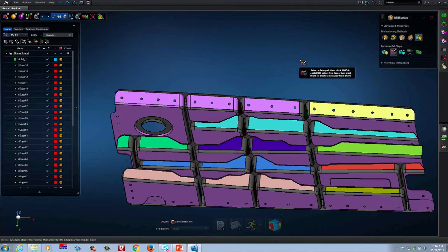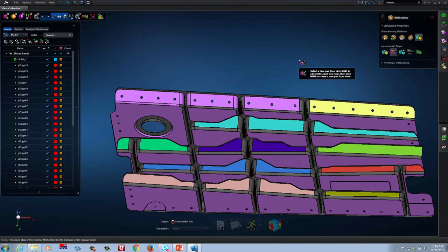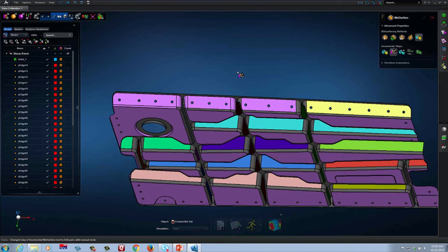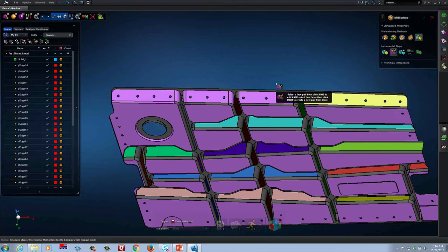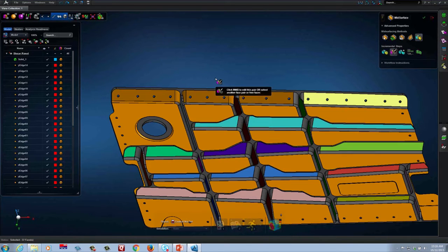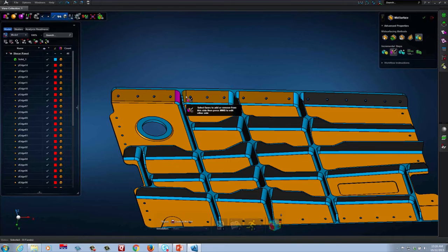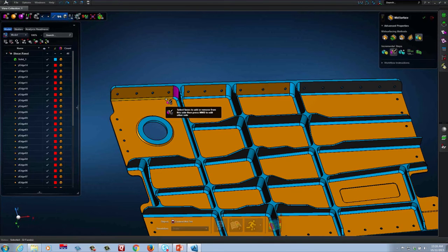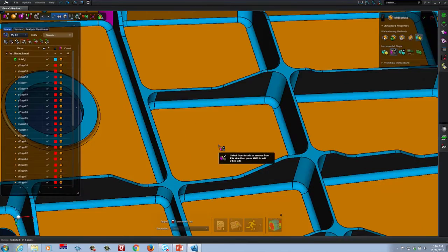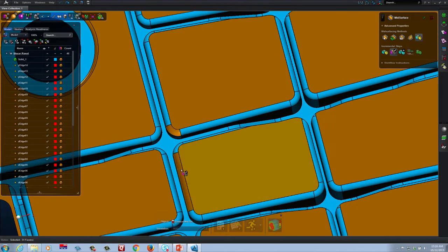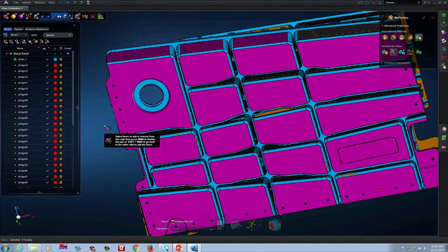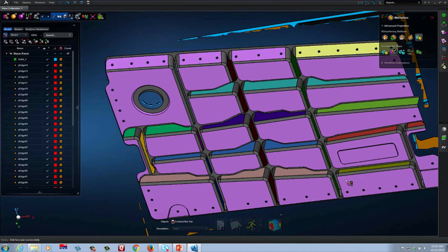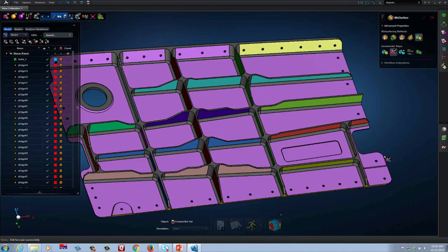Of course, Apex has multiple undos, so even if you had created it, you could actually undo if you made something that you didn't want later. So I also see that I have a few other little fillets that were included. So it was good to remove them over here, so it's probably good to remove them in these other areas. Let's go ahead and do that real quickly here. We'll find the filleted areas that were included, basically due to some tolerancing issues, perhaps. We'll remove those, and we will have edited our face pair definition. So now we've got something that doesn't include those fillets.